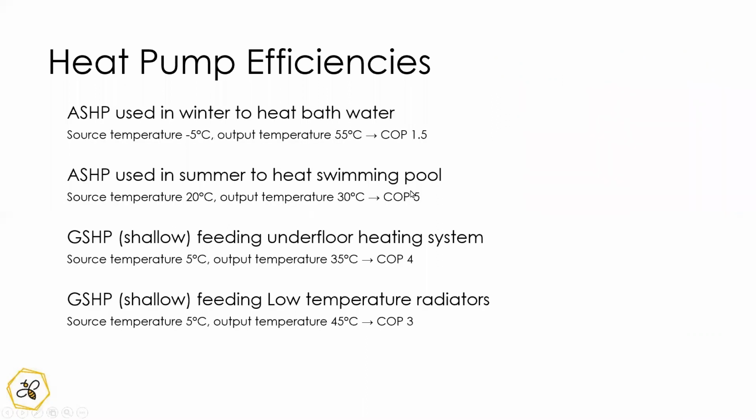Who knew? Look, Florence, can I just add that there is a Carnot cycle equation, which is relatively complex, but if you simplify it, it means that every time you double the temperature difference, you're halving the efficiency. So if, for instance, the outside temperature is 10 degrees and your system's working at 35, that's a 25-degree difference.